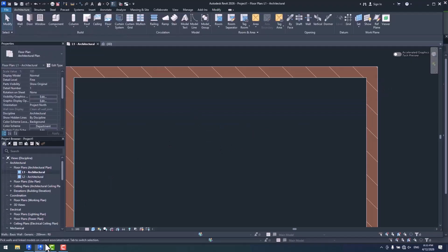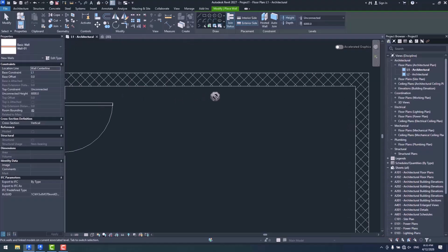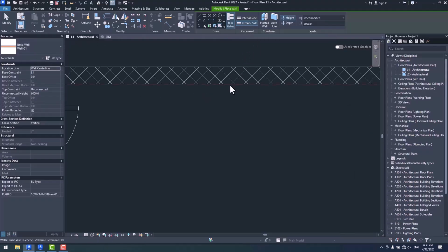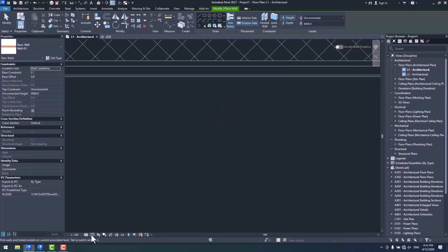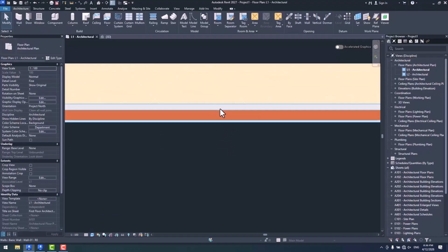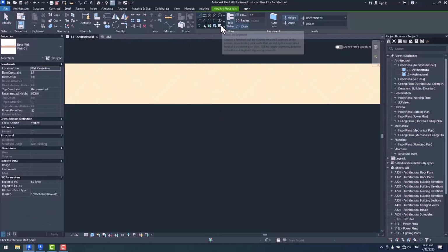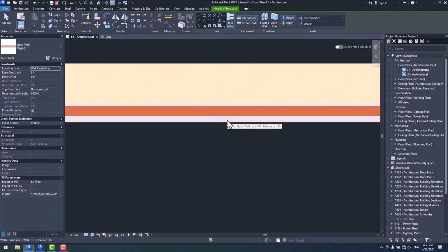In Revit 27, though, we don't really have to do this. We can control the course that we want to set the wall in before setting the walls. Let me show you an example in Revit 27 as well. I'm setting this wall here based on the exterior location line. Give me some colors, actually. Yeah, way better. Anyway, as you can see, this 5cm layer is set on this side. I'm going to remove it. Let's try this one more time, this time based on the interior location line. And here we go. So to put it simply then, guys, we got a better control now.